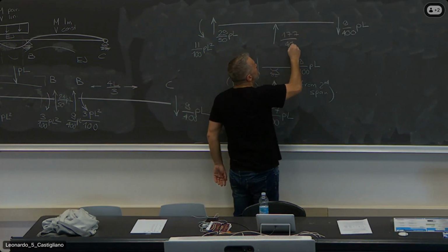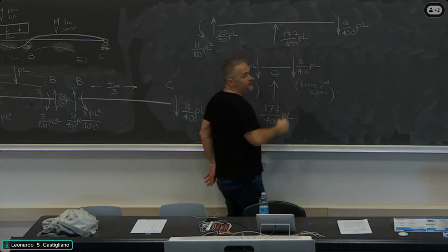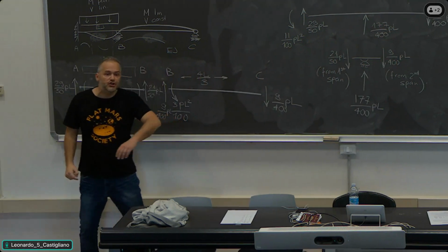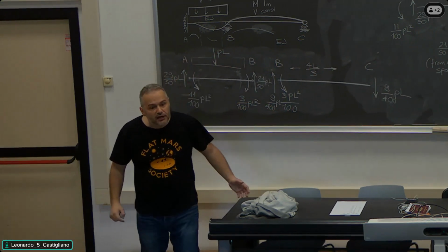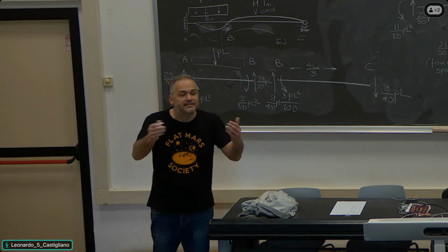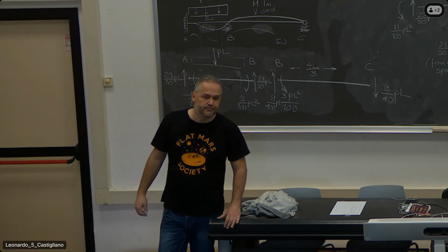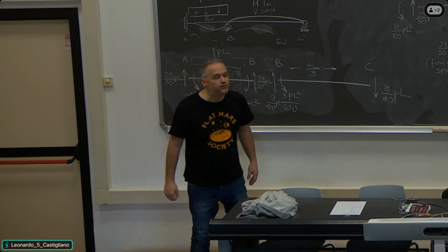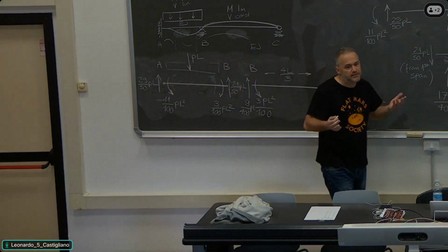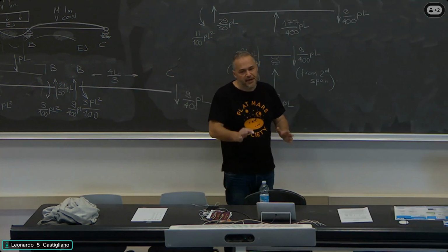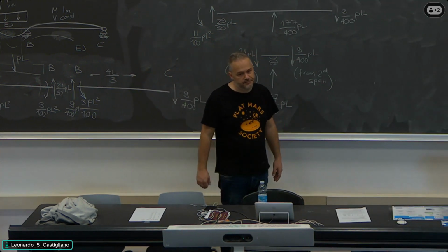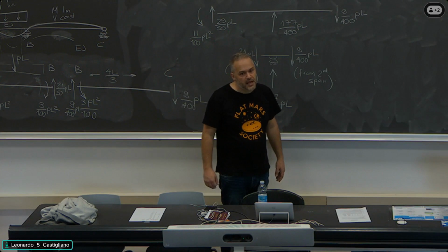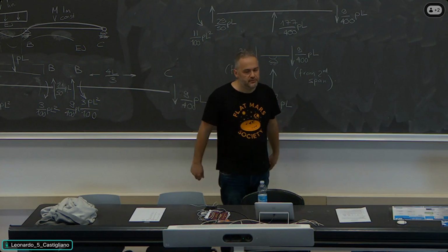And as you see, this restraint force is neither equal to the shear force to the left, nor to the shear force to the right. It's the sum of the two. And of course, one may ask, is it always the sum of the two shear forces? No, it depends on the sign of the shear forces. Clearly, it depends on the sign of the shear forces. But it's always the operation between the two forces. It's the combination.